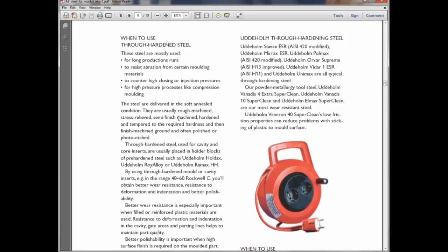This is the criterion for bending. Even in through hardening, you will come across bending and deflections. Deflections and bendings are always there after through hardening, because we have applied so much temperature that the part can deflect from its original shape.